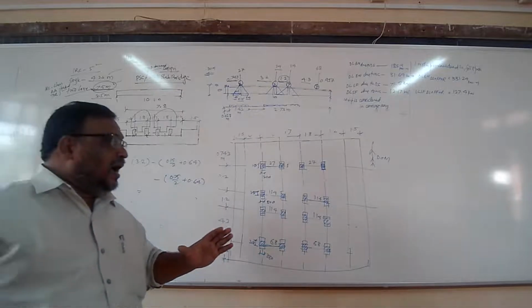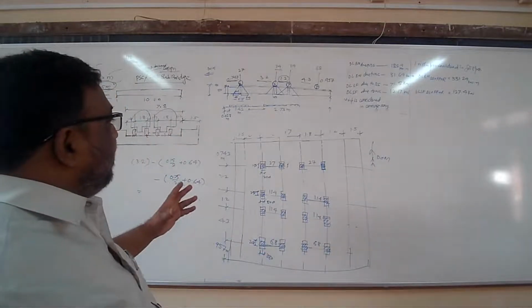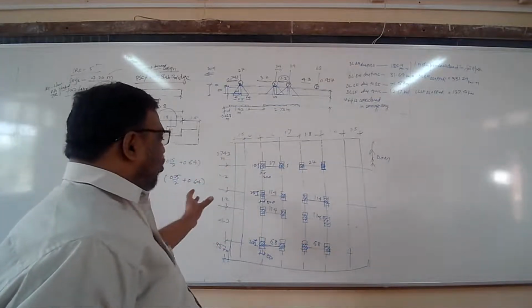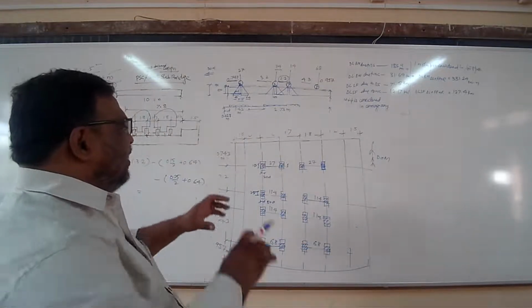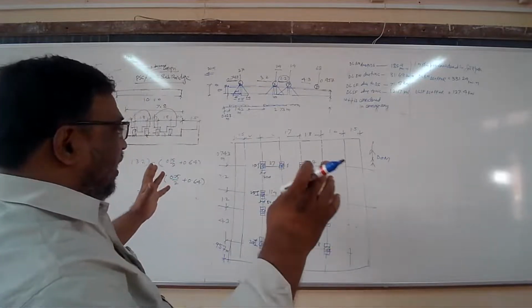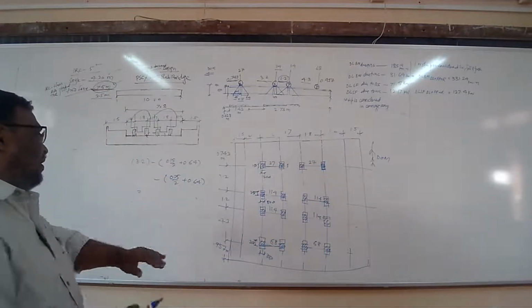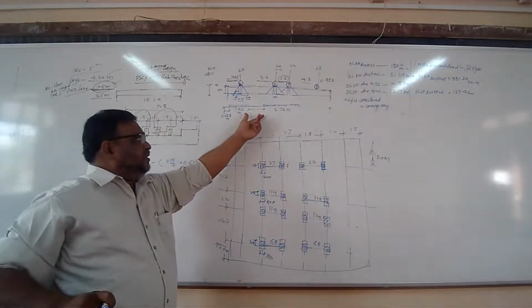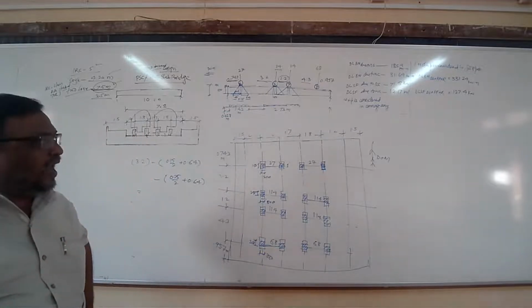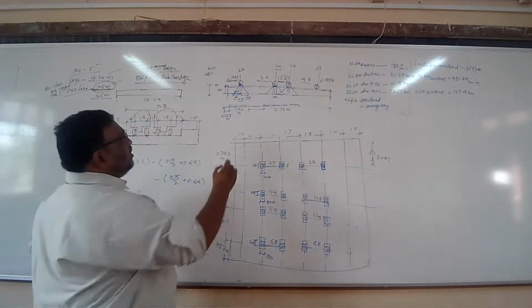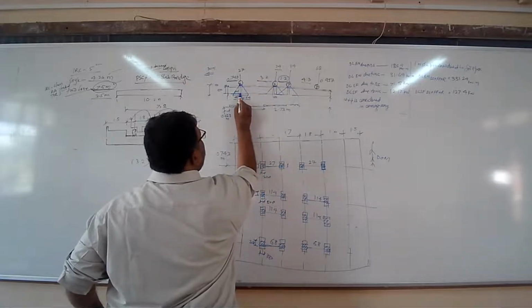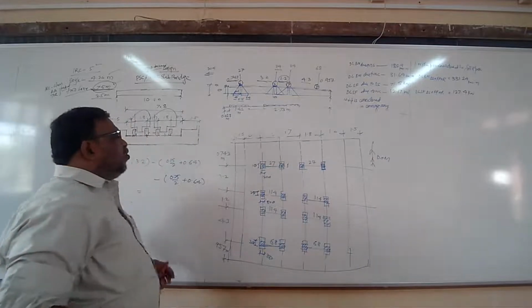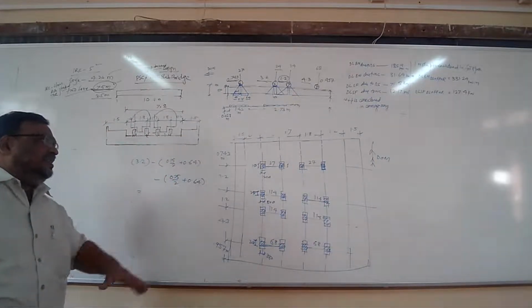We need to find where the load is acting, on how much it is acting, what the intensity is, how it is along the span, how it is across the span, what the contact length is, over what area the dispersion will happen, what that patch area is. All of that has to be calculated. So here we are locating this position where there is no load acting. Because the center to center distance is 3.2, I subtracted this much from it, and this much from here, so I will get the remaining distance. That's all. There is nothing else, it is simple geometry, just distances.